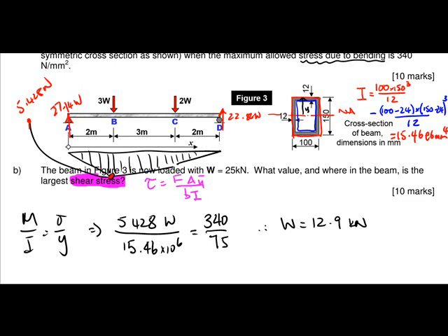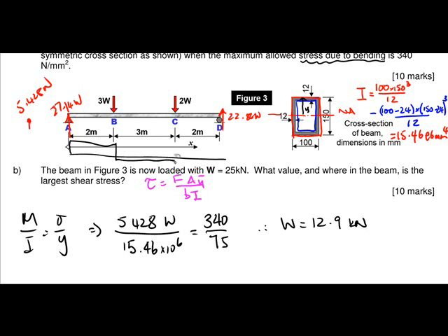For part B, we need the shear force to give us the shear stress. So let's remove that bit. The shear force diagram goes up, goes along, comes back down, and goes along down to here and across like that. The two big shear force values are either this one or this one.